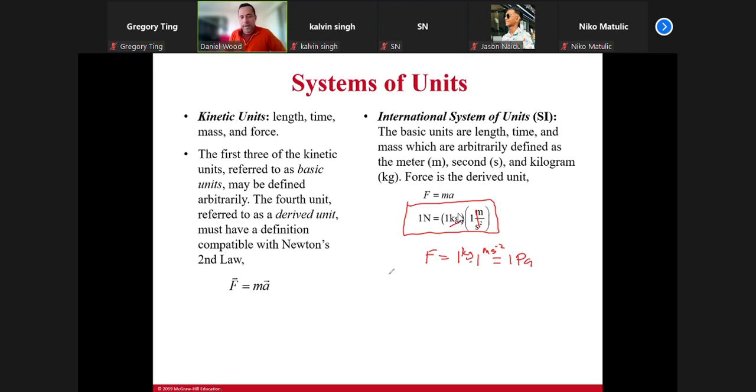And in actual fact, it can be very handy when you're doing this. A very common equation that we would use in aerospace is coefficient of lift equals lift over half rho v squared s, where this is the lift force acting on the aircraft, this is density, this is velocity squared, and this is the planform area of our aircraft, yeah?